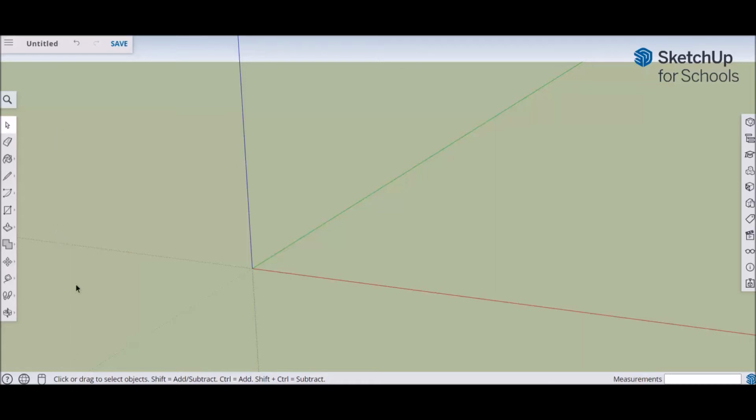So first of all, we want to look for a rectangle. So click rectangle, we want this rectangle, and then you just click and drag to draw your rectangle. And down in the bottom right hand side, you'll see the dimensions. So I'm just going to draw one out quite big. And then if I don't click anywhere else, once I let go, I can just type and change my dimensions. So if I change the dimensions of this rectangle to be 80, 80, and press enter, see, it's made my rectangle 80 by 80 millimeters.